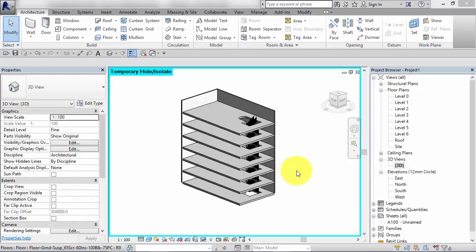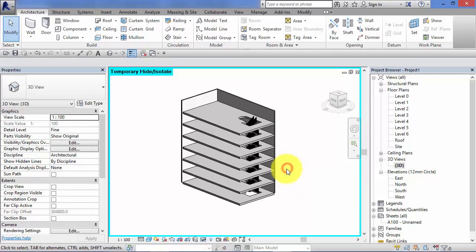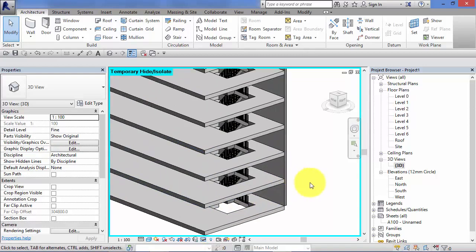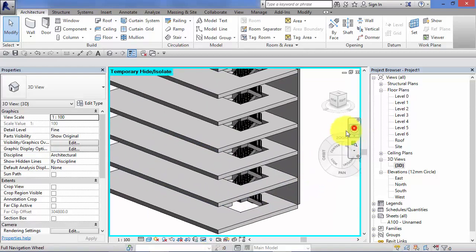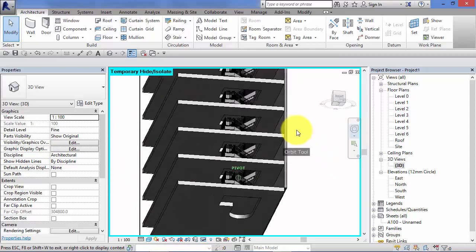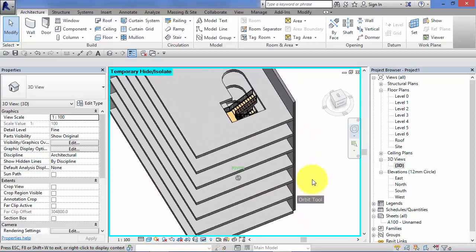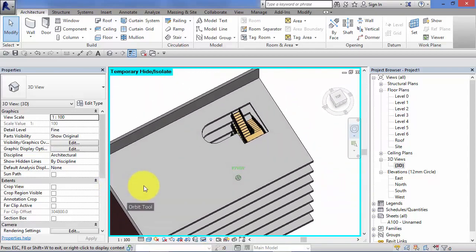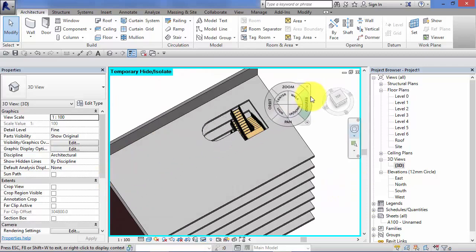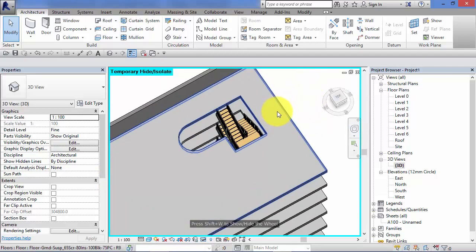A really neat feature of shaft openings is that they only cut through certain categories of Revit elements. They obviously cut through floors because we've just seen how that works. They also cut through ceiling objects and they cut through roofs as well. But apart from that, they don't affect any other element in your model. So in this example, you can see that I've added a staircase up the full height of the building. There is the effect of the shaft opening that we previously created.